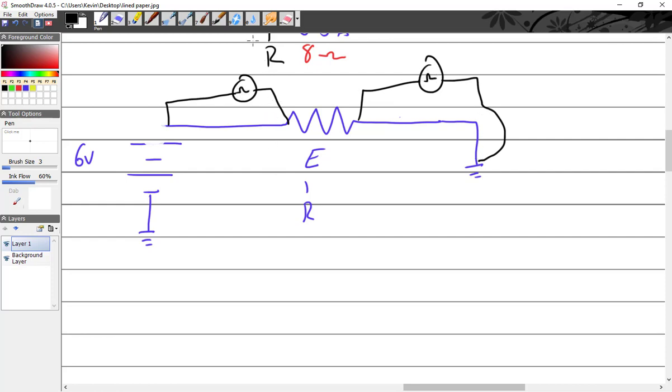And with no power on at all, with the Simpson meter, I basically show it's 0. I zero out my meter, not infinite. Infinite's open. So I say, oh, it's like 0 ohms. I can't really read anything. It's like 0.0000 something. It just looks like 0 to me. I'm going to call it 0 ohms. All right? And say, okay, that's fine. Let's just give this some value right here.